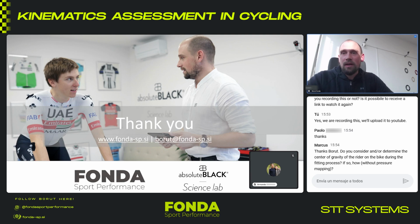And this is also the philosophy I'm pursuing as a bike fitter, except I'm not using floating pedals, I'm using force pedals measuring torque. And I want to minimize the torque that's happening rotationally, so around the z-axis, and also the lateral torque, how much you're pronating and supinating. So I don't set up based on how I see the fit, but we set the cleats basically so that the output at the end is as centered as possible.